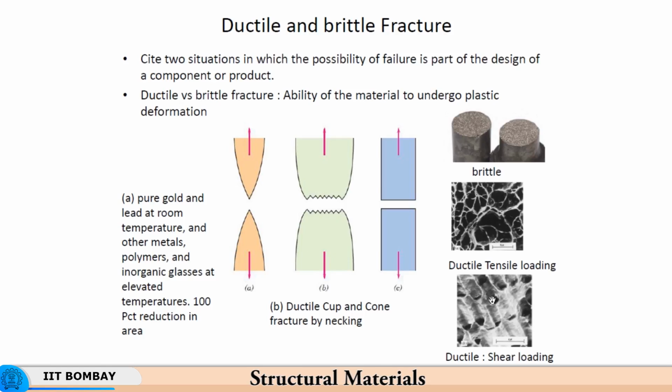But then as the plastic deformation progresses, although you might find that deformation is uniform outside, there is absolutely no non-uniformity in deformation, internally, you will find that these ligaments are deforming and getting thinner and thinner. So, as this happens, these voids continue to grow in size, and when these voids continue to grow in size, the ligaments can snap between two voids and the two voids can coalesce. So, which means that two voids can get integrated into a single bigger void.